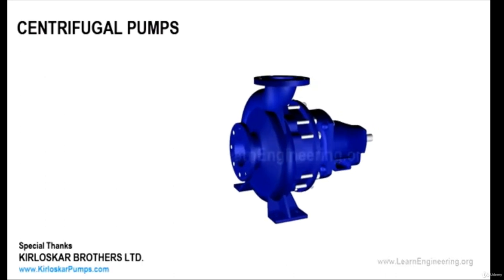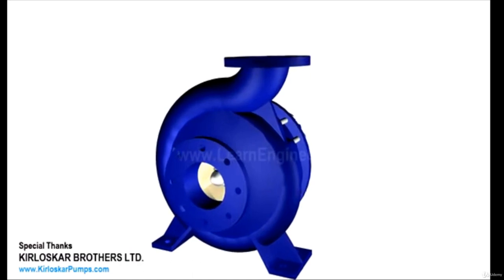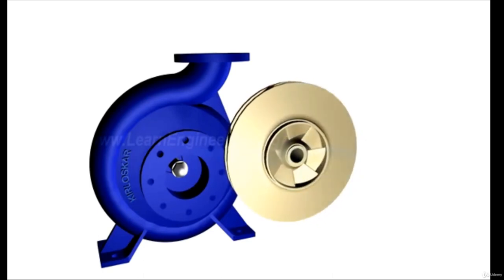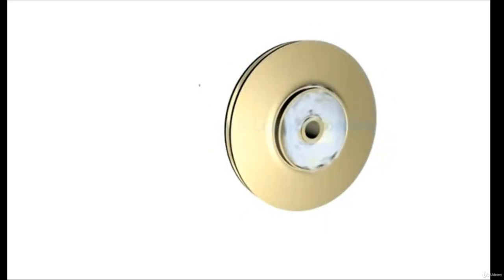Centrifugal pumps are the most preferred pumping devices in the hydraulic world. In this video, we will have a conceptual overview of the working of centrifugal pumps. At the heart of the system lies the impeller. It has a series of curved vanes fitted inside shroud plates. The impeller is always immersed in water. When the impeller is made to rotate, it makes the fluid surrounding it also rotate.